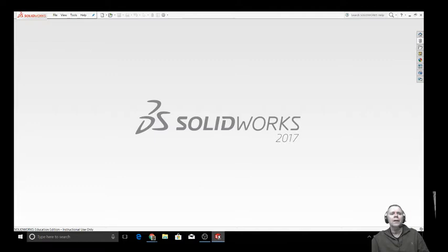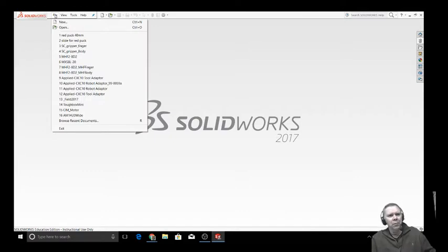Now, when you first boot up Solidworks, you're going to be greeted with this wonderful screen right here. Let's just take you on a little tour of some of the features of Solidworks. Solidworks is what's called a parametric modeling tool, which means that everything is designed through parameters. You set up the length of a line, the relationship of one line to another, how a point coincides with another point. It's all done parametrically, and these parameters build up until finally you create your final drawing.